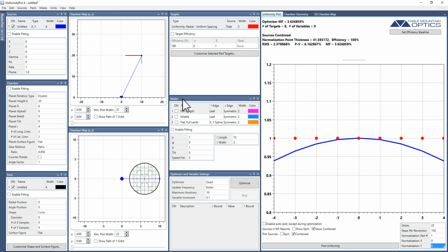Optimization is really an art. One of its challenges is getting stuck in a local minimum and not finding a global solution. So for this reason, I'll frequently hop back and forth between various optimizers, and I'll also start with different mask starting points. And that's what I've done here. Basically, I've created 3 masks at different starting points. So let's look at them.